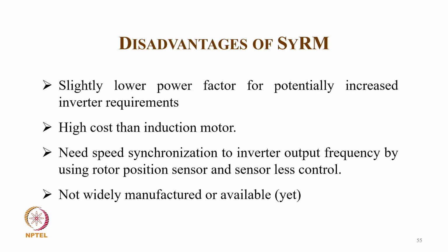And the disadvantages are slightly lower power factor, potentially increased inverter requirement, higher cost than an induction motor, and the need for speed synchronization to the inverter output frequency by using a rotor position sensor or sensorless control. It is also not widely manufactured or available yet.